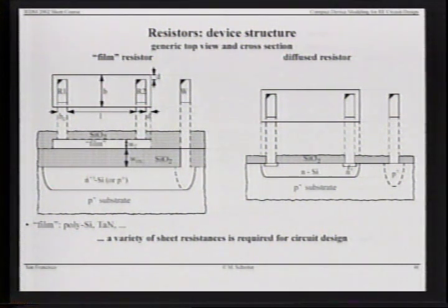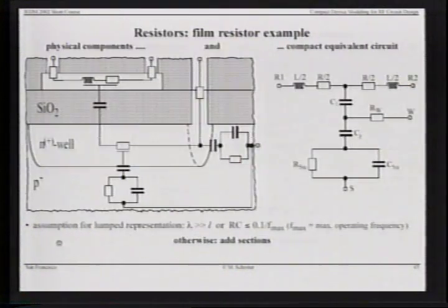And underneath this resistor structure, there can be a well, either an N or a P well, so it's an isolation implant or a highly doped N well. And that changes the equivalent circuit, as we see in the close-up here. But let's focus first on the resistor structure here. This is the desired resistor. These are parasitic end contact resistances.